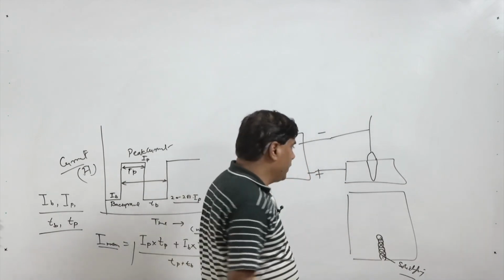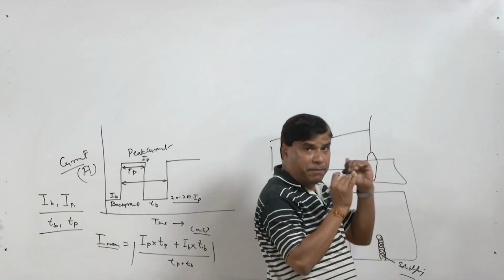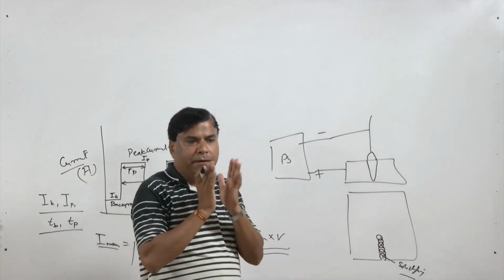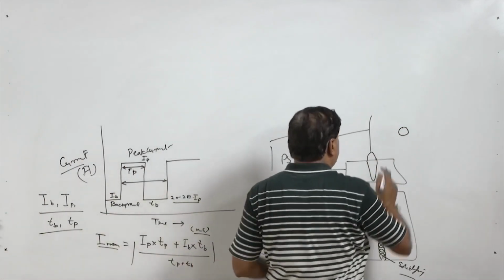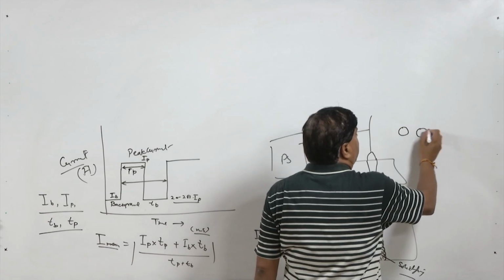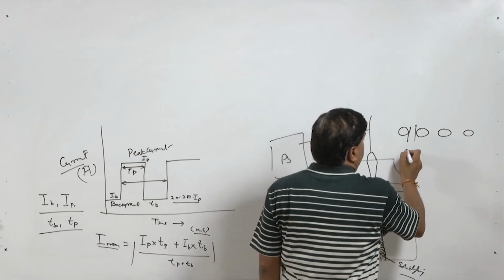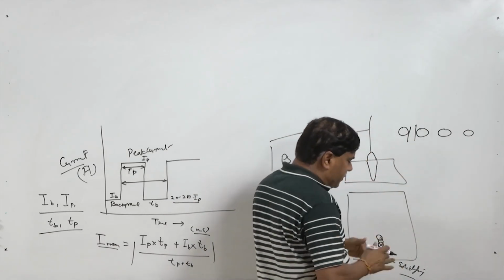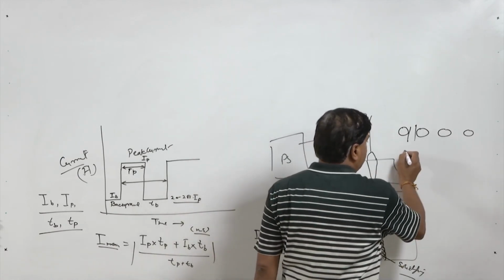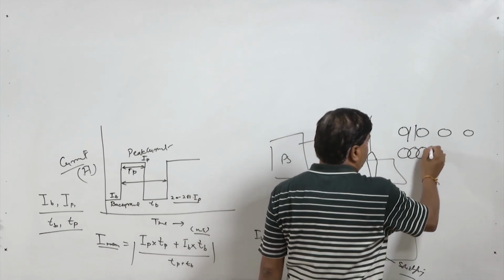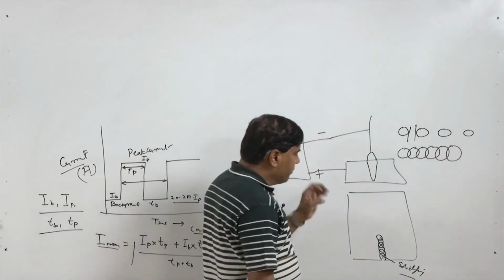It has two effects. One, if the frequency of the pulse is very low, meaning the peak current pulse comes after a long time, then when the arc is moving, the gap may be very wide and it may result in unmelted zones between the different pulses. So this is to be synchronized well with the welding speed as well as the frequency at which pulses are given, so that they overlap enough to produce through-thickness melting and a continuous weld is made.